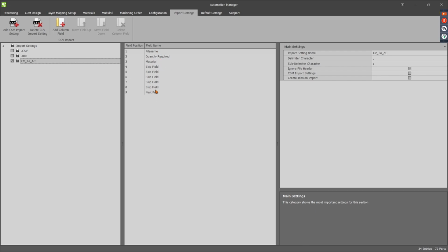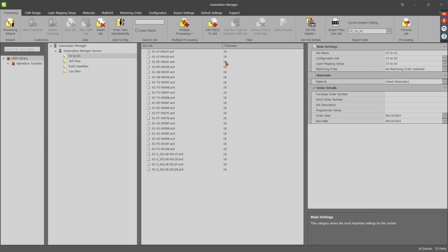If we then imported that, which we will go through when we do the advanced user guide, you will see that all imported. We'll get this set up linked with that CSV, so you can take that away if you decide to use it, and then essentially import the files with all the extra information. So if you've got a job with 4 materials in, it will assign the material to those individual parts, which means it won't nest them in the wrong material, and it will nest them separately, and you'll have everything done complete. So again, using CSV is very powerful.